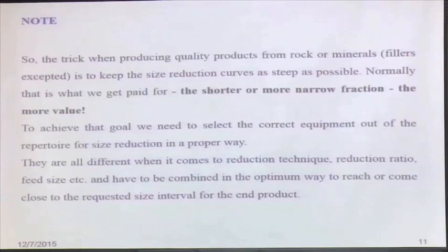The trick when producing quality products from rock or minerals is to keep the size reduction curve as steep as possible. The shorter or narrower the fraction, the more the value. It is easier to say, but very difficult to control. To achieve that goal, we need to select the correct equipment and the scale of operations.